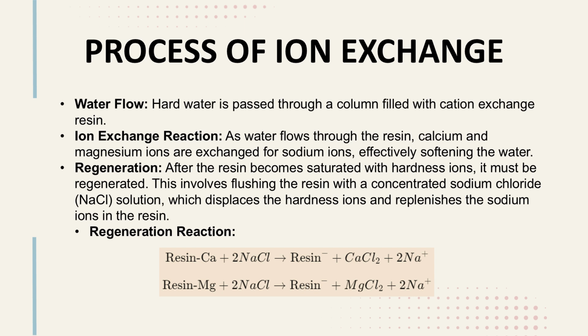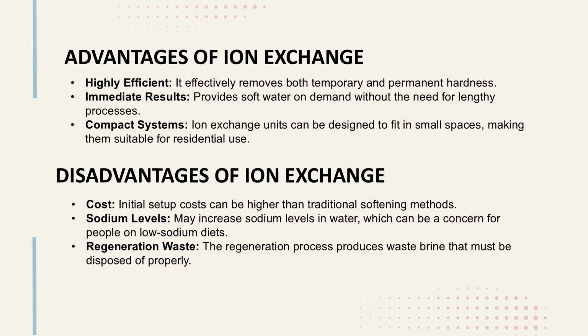But this resin doesn't last forever. It gets saturated with the hardness ions over time. When that happens, it must undergo regeneration. This is done by flushing the resin with a concentrated solution of sodium chloride, NaCl. The sodium ions in the salt solution displace the calcium and magnesium ions, replenishing the resin, so it can continue softening water effectively. Let's review the advantages and disadvantages of the ion exchange method.